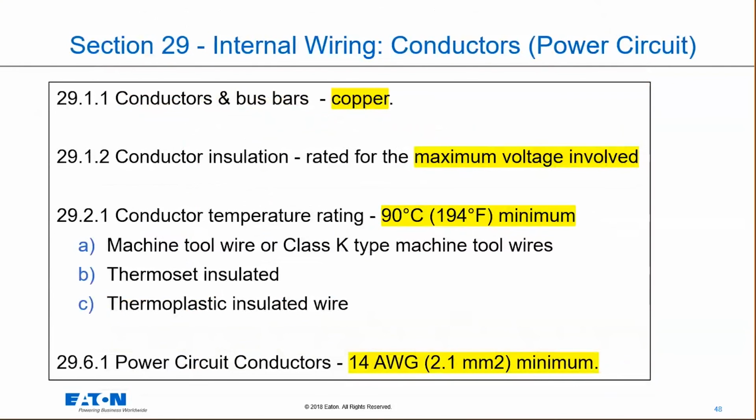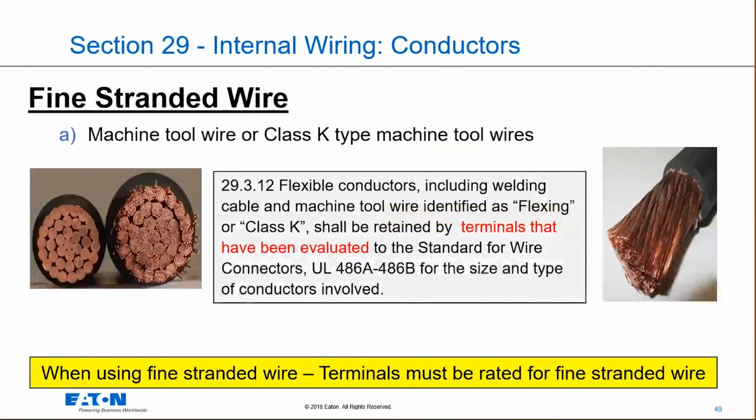We talked about fine stranded wire. Just make sure you're aware, guys, that when you're talking about stranding of wires and what they are, you have to make sure that your terminals are labeled for those types of wires and cables. So when using fine stranded wires, your terminals must be rated for fine stranded wire. You definitely want to look at that, because there are cases out there where I've seen people using it, and really it's not designed to do that.